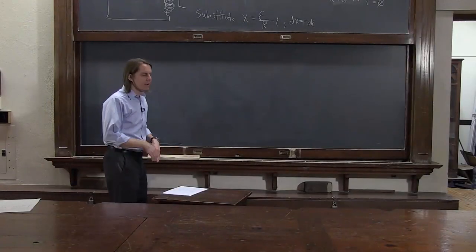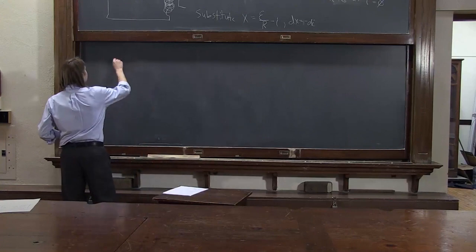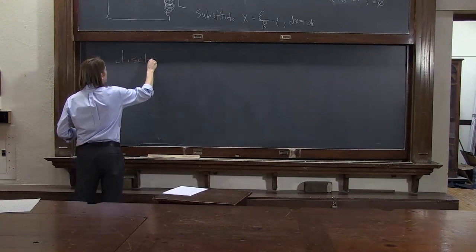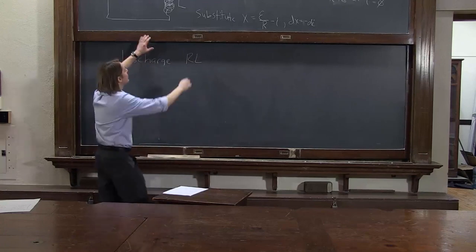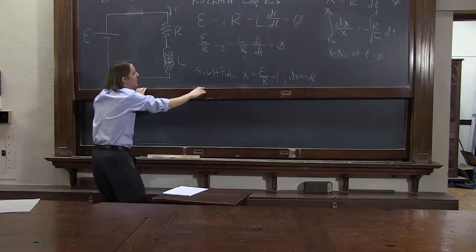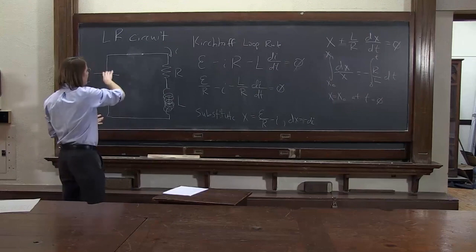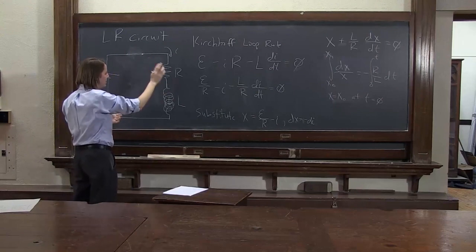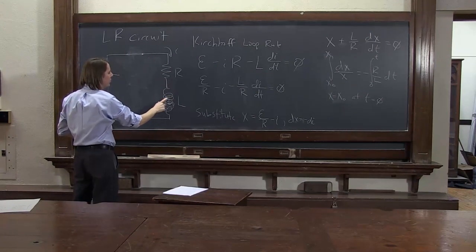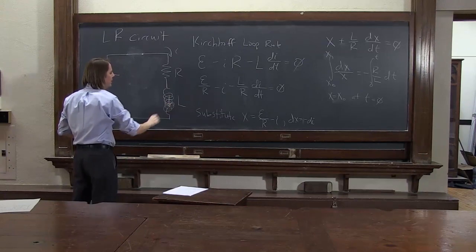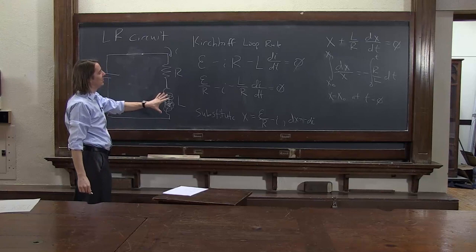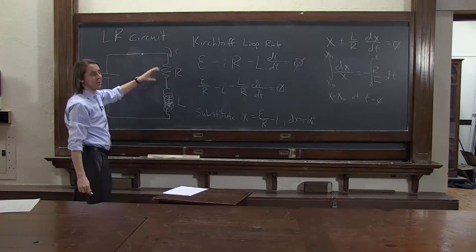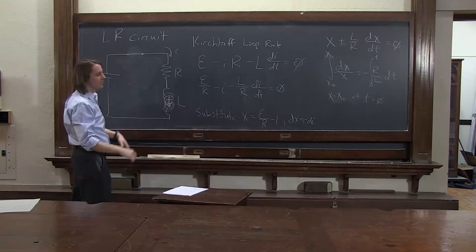We have our nice B field in our inductor. Now let's discharge the RL. So let's look at the circuit again. It was like this. The battery caused current to flow. We reached a steady state where there's nice current going through the inductor. We have a nice B field now inside the inductor, but it's constant. So there's no back EMF. All the potential drop is across the resistor, and everyone is happy.